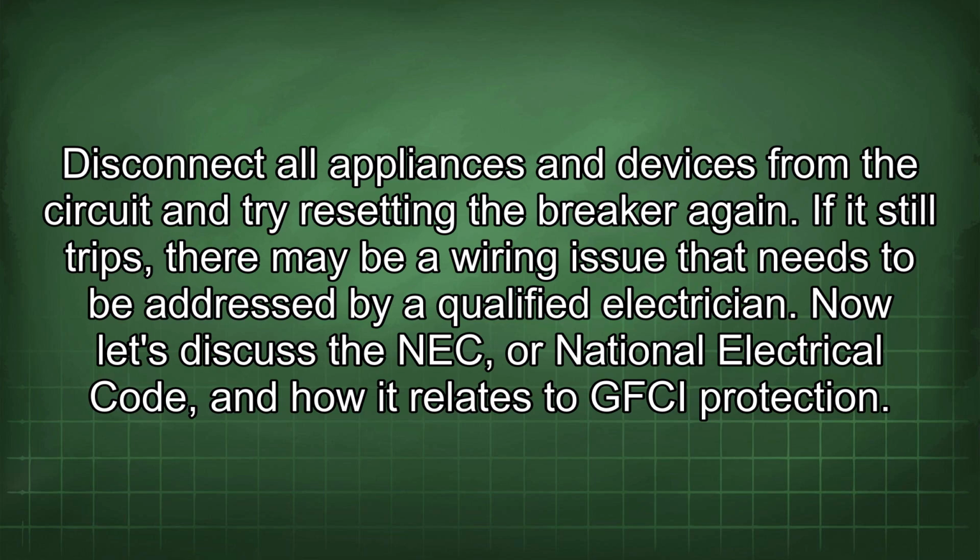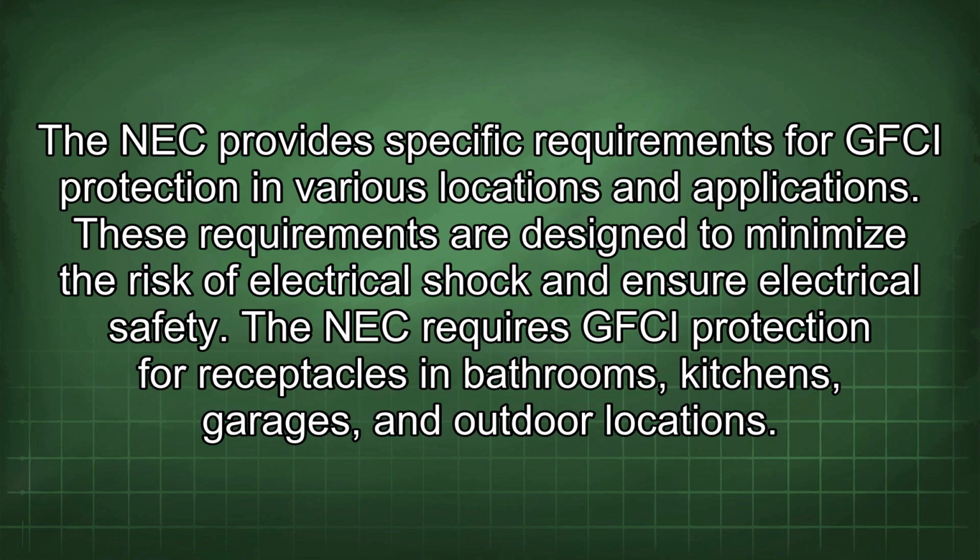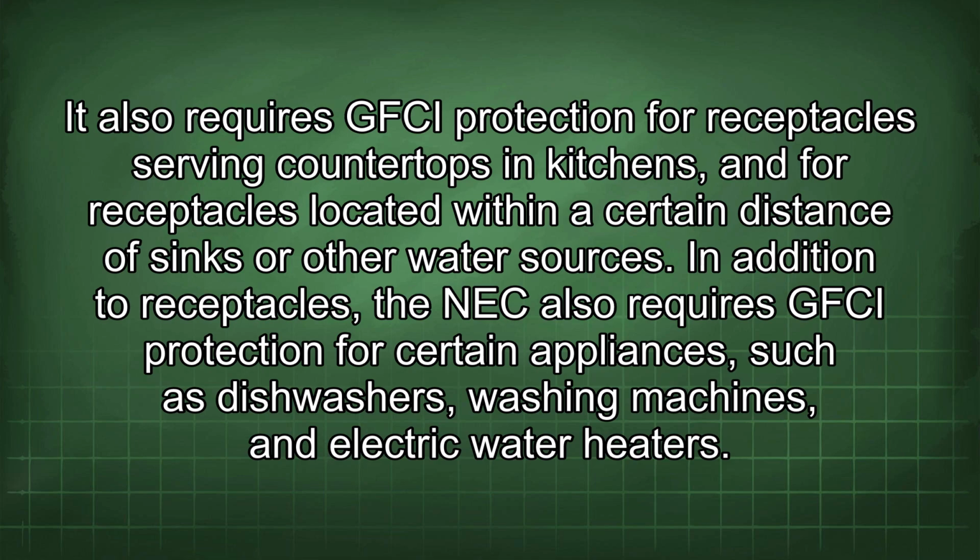Now let's discuss the NEC, or National Electrical Code, and how it relates to GFCI protection. The NEC provides specific requirements for GFCI protection in various locations and applications. These requirements are designed to minimize the risk of electrical shock and ensure electrical safety. The NEC requires GFCI protection for receptacles in bathrooms, kitchens, garages, and outdoor locations. It also requires GFCI protection for receptacles serving countertops in kitchens and for receptacles located within a certain distance of sinks or other water sources.